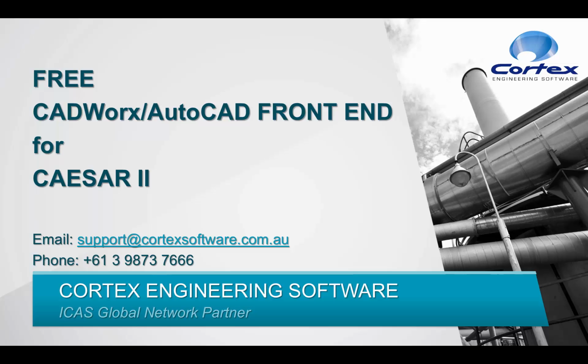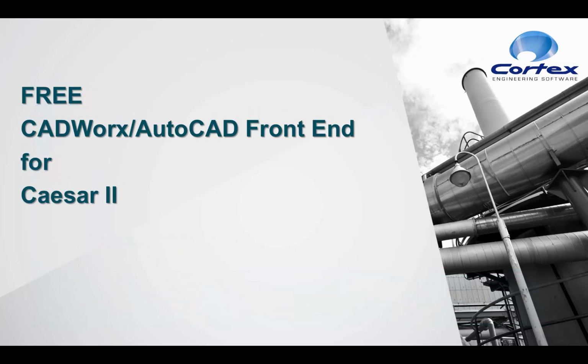This tutorial will introduce you to a great graphical interface to Caesar 2 that offers an extremely efficient method of creating accurate specification-based Caesar 2 models. The graphical interface I'm about to demonstrate is available as a free download. It is essentially a demo version of CADWorx that will read and write native Caesar 2 files. Now, CADWorx sits over the top of AutoCAD, so to use this interface you'll need access to AutoCAD.